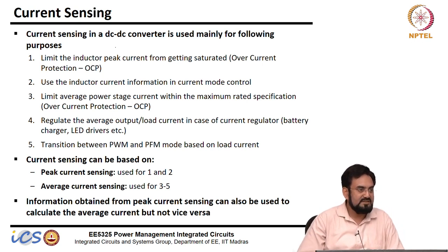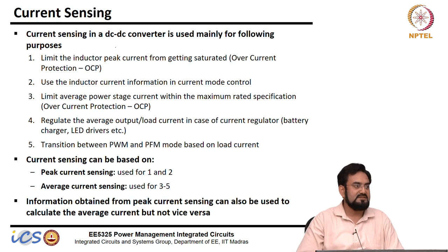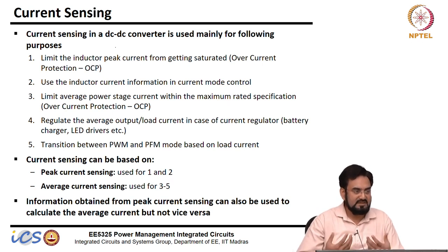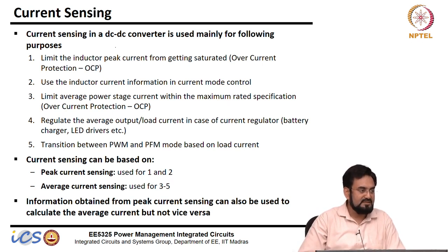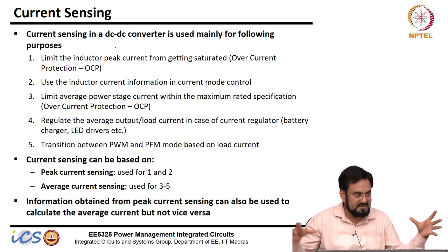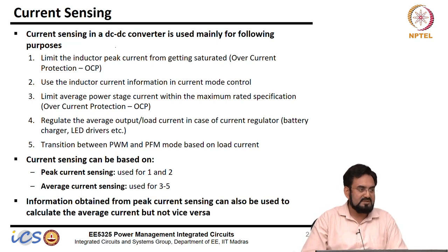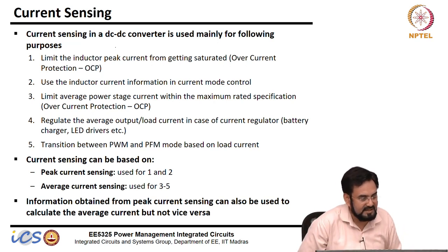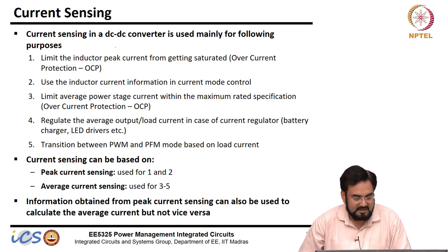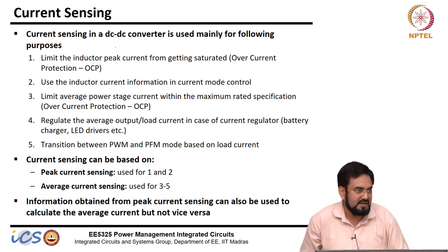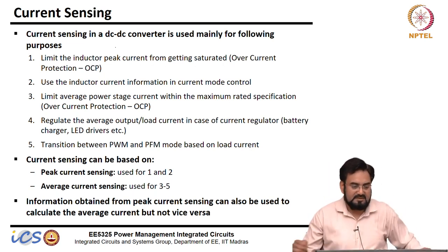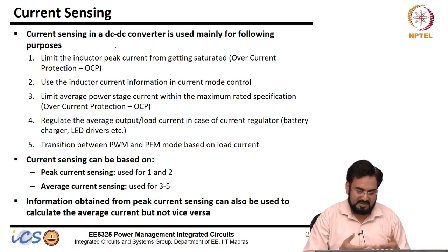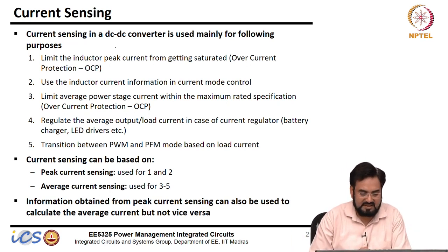The main reason is that we want to protect our device from short circuit or when the load becomes very high. We want to protect MOSFETs, routings, metal, everything, because they have a certain current rating, and the MOSFETs you have designed cannot handle more than the current you designed for. They will heat up and may melt, or your devices may break, anything might happen.